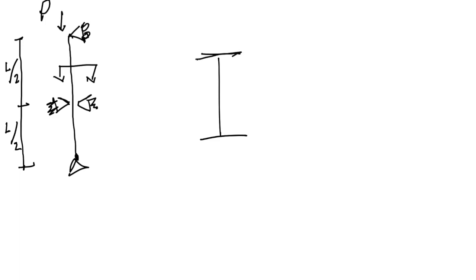So this flange here is what it's kind of like we're looking down on the top of this I-beam. This I-beam is restrained from deflecting in this direction by these guys, but it can deflect out of the page also. So there's two axes of deflection. There's one in this direction, and there's one out of the page. And so if we have our I-beam, say it's a W200 by 34, we can go ahead and look up all the material properties.